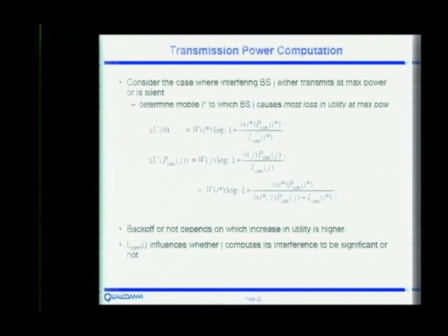Right. So it compares these two quantities and makes a greedy decision saying which of these matters more, and it takes the right one, transmit or maximum. So why should we look at the sum rate, maybe looking at the other guy's rate also? You should look at the other guy's rate because you may not be a dominant interferer to the other guy. So for example, if these two quantities are very close to each other, if your Hij times P max is very small compared to I naught, this tells you are not really causing most of the interference, and I is not the dominant interference factor. So if these two quantities are very close to each other, then it should go. Because it's not really a significant interference to link I, but it's getting some gain in its own rate times WI, so it should go.